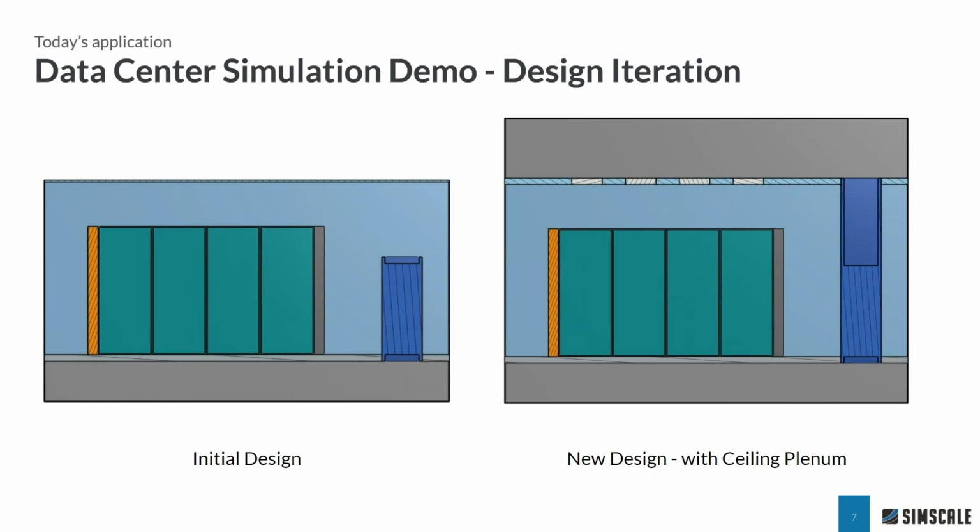And then I think probably one of the most important parts is you'll notice over on the right, the CRAC unit is essentially attached to the ceiling. It's got a duct there that attaches right to the ceiling, so it only pulls that hot air, and it provides suction in the hot aisle. Of course, here we do see that floor plenum, so it's worth checking out there. These are, of course, downflow CRACs.